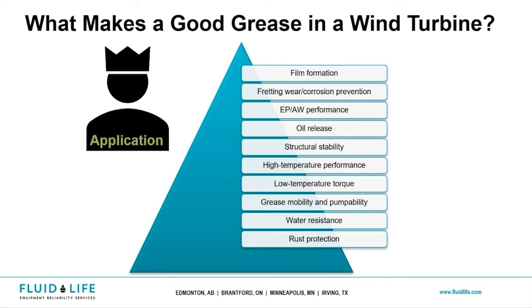So understanding your ambient environment, say you're at a wind farm that's a lot more humid, right? Or say you don't have the service covers on the nacelle closed and you're letting dust in, in Texas, for example, right? And there's a lot of heat trapped inside the hub and the nacelle, right? And then also taken into account are service intervals, with current procedures that are common in wind, with how they're purging the grease and pumping new stuff in. You've got to keep in mind that there could be a lot of water ingression and a lot of rust and oxidation that becomes an issue.